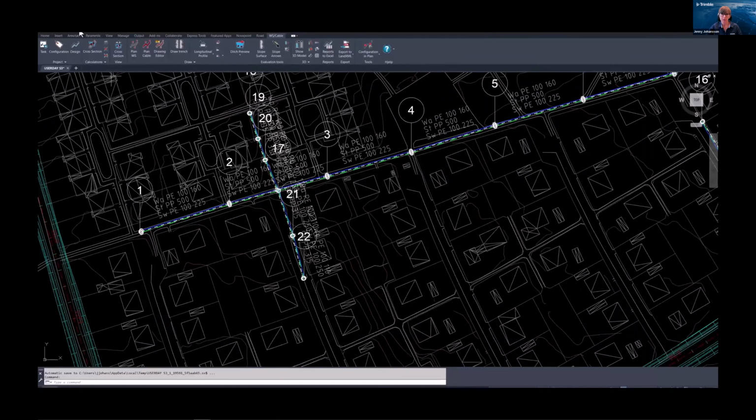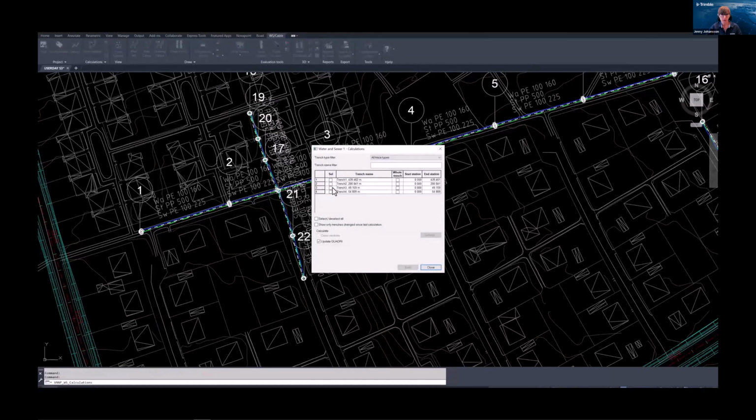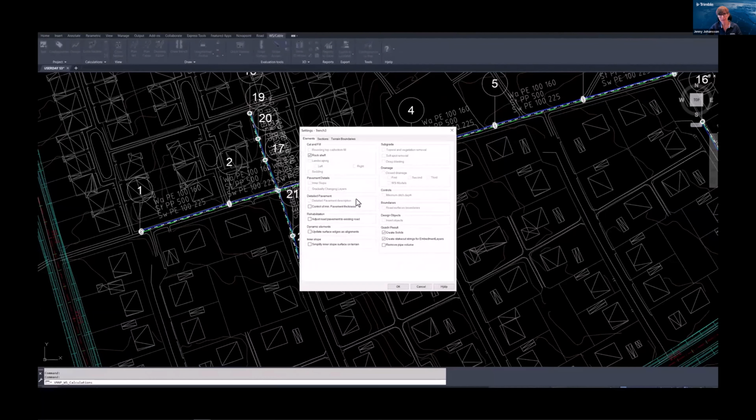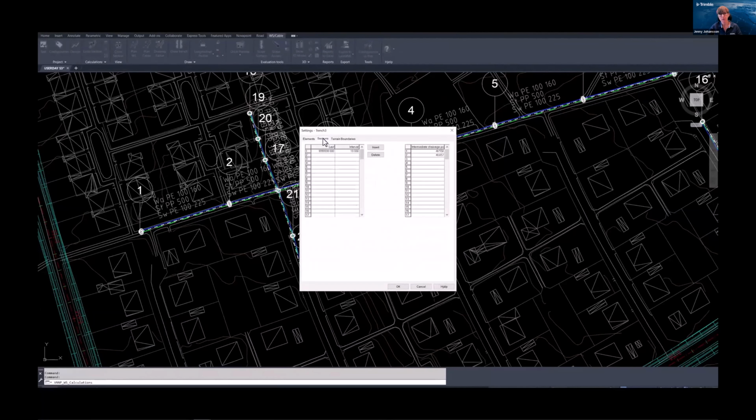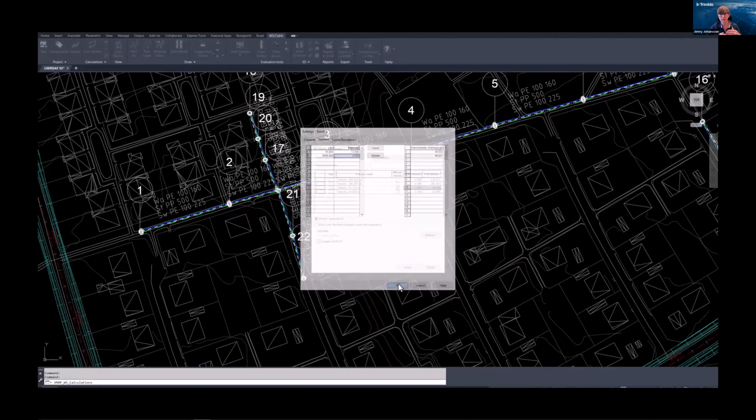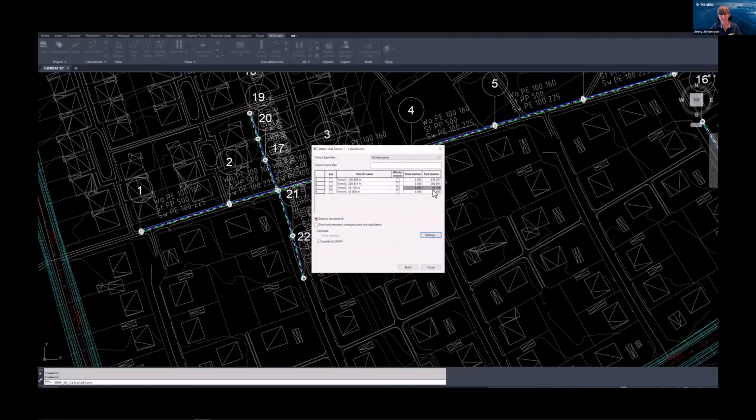So what we need to do now is to recalculate both trenches. And now I mark one trench at a time to be able to change the settings for the calculation. Then I can go to the section tab and I can set a tighter interval for the crossing situation, so we get even narrower and more exact appearance there.